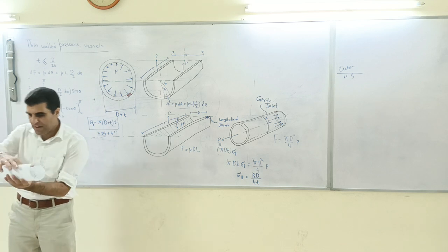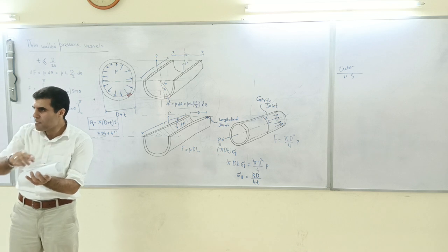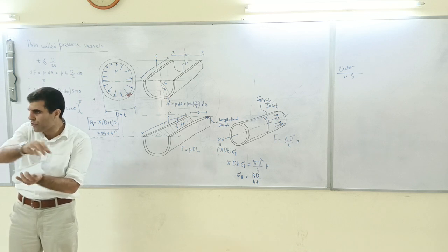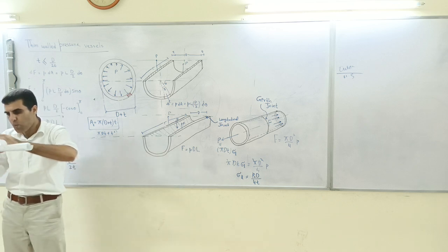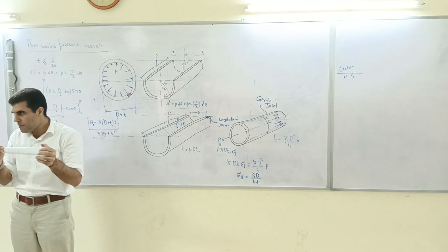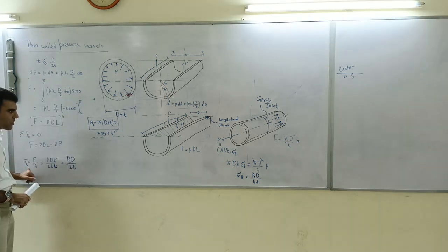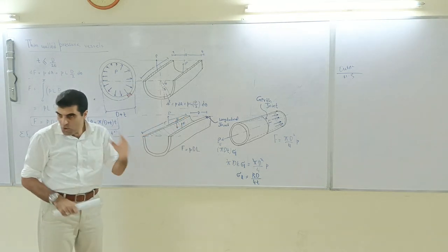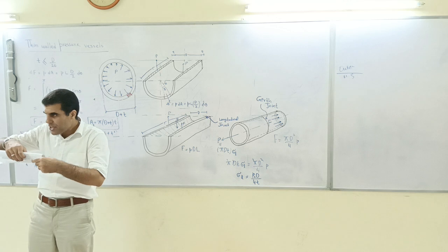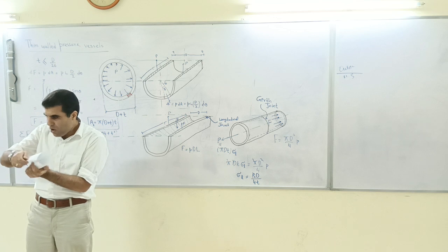You can have two joints if I put another paper on top of it and staple it by two rows of staples. Do you understand my point? In my case, it's just one row of staples. So stress T you have worked out. You multiply that with the thickness times length. You get the force, that force which is opening it up.